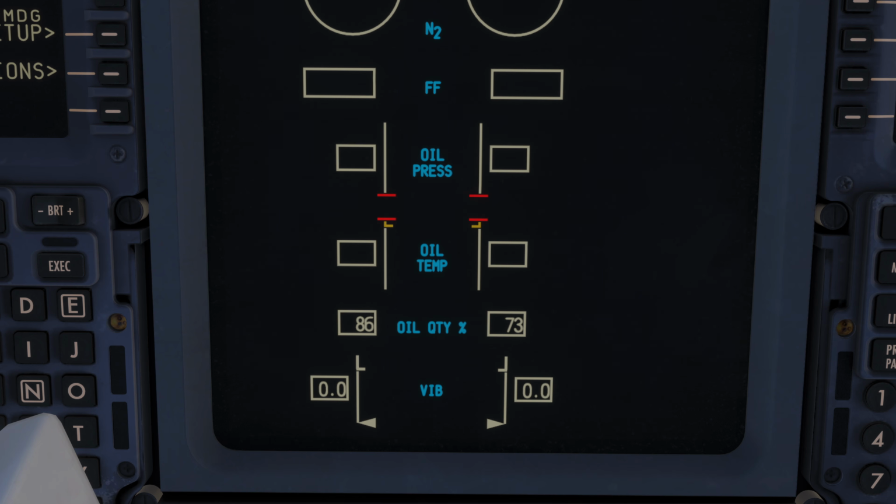Now, here again, all you need to know is that the stronger the engines vibrate, the worse of a maintenance condition they have, and if a certain limit is exceeded, that tells us that there is such a strong imbalance in the rotating parts of the engines that damage may occur. In the worst case, the rupture, for example, of a fan blade or an entire turbine. Now that's what vibration is used for. And this basically covers the types of engine instruments that we are seeing and that we're using to control our engines and to monitor our engines.